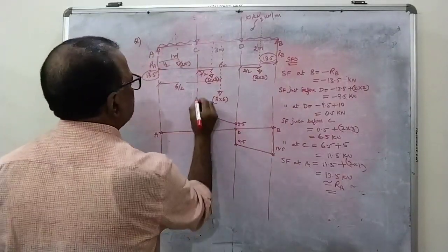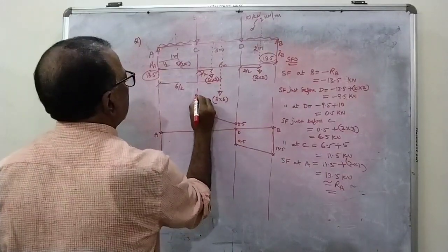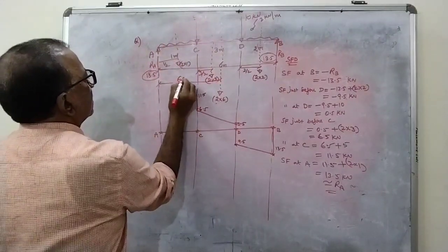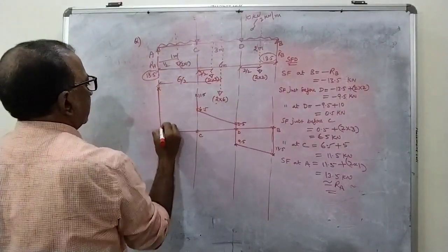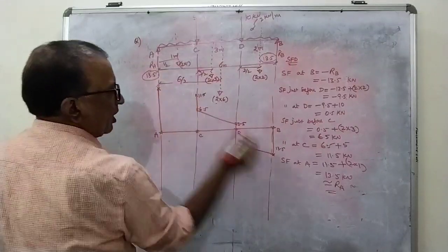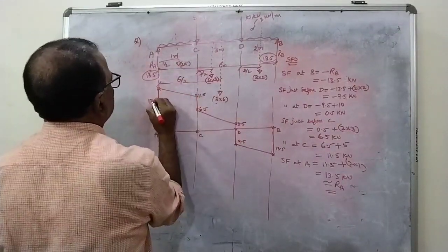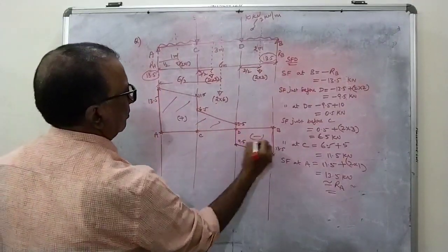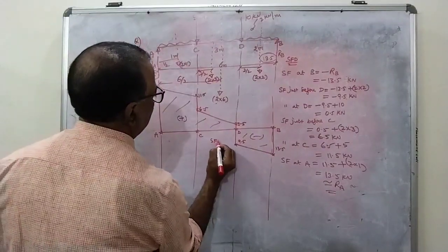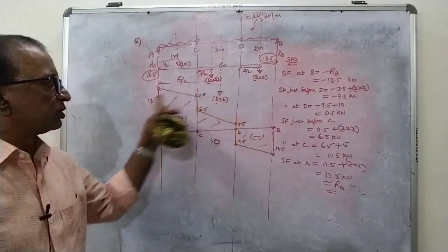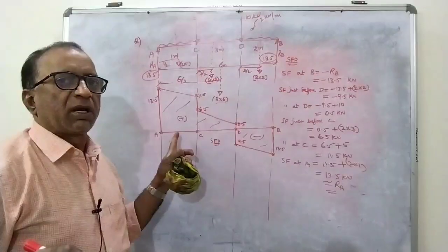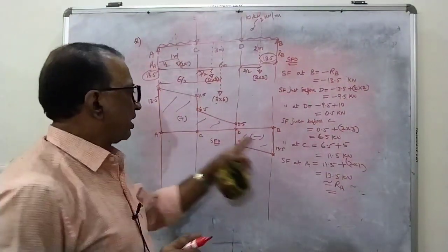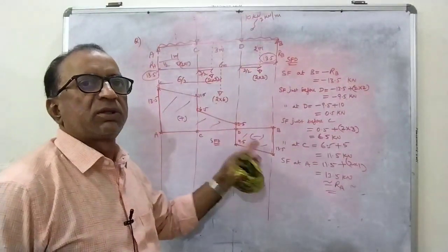At C, it has increased to 11.5 due to this point load. And just by coming to A, from 11.5 it has increased to 13.5. This is your shear force. So already I told you, when you go through this total shear force diagram, your maximum shear force is nothing but either at A or B, both we got it as same, that is equal to 13.5.